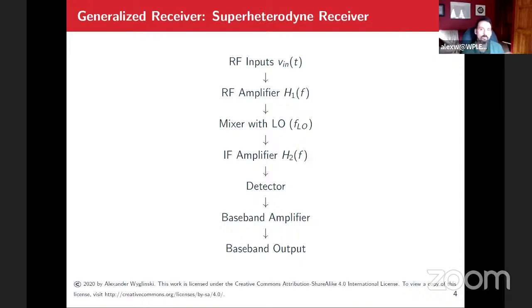They're more prone to drift, right? They're causing the frequency offsets. So it's like there's this trade-off. You want to go to higher frequencies, but you're going to need a really good local oscillator. So there's some tricks that you can pull in terms of creating a local oscillator that's capable of transmitting, as well as what we're going to be seeing here, receiving signals.